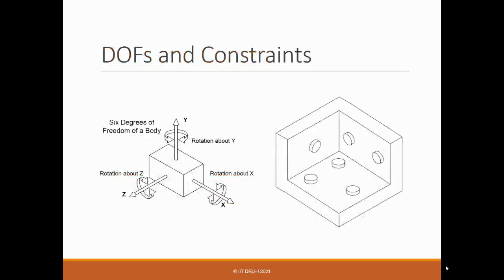Similarly, if you start putting constraints, then we can remove them one by one, and at the max, what you can remove is 6 degrees of freedom by using these constraints, point contacts or contacts. For instance, here is one example: suppose you want to place the frame here, this 3-2-1 configuration is enough. So this is one way. There are a lot of other possibilities, which we can check later, or you can even think about it.